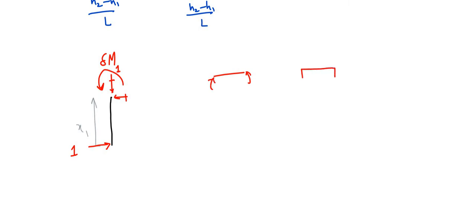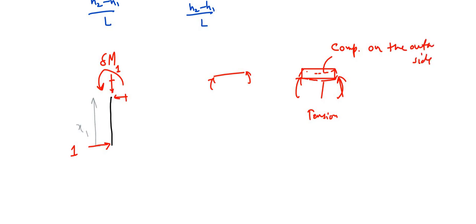अच्छा ये बात भी याद रखिएगा कि हम फ्रेम के अंदर जो पॉजिटिव बेंडिंग है बीम में, तो आपको पता है कि बीम में हम ये पॉजिटिव बेंडिंग लेते रहे हैं, यानी जो मोमेंट की डायरेक्शन है, इस डायरेक्शन से जो स्ट्रेसेस प्रोड्यूस होंगी, ऊपर कंप्रेशन प्रोड्यूस होगी, इस तरफ कंप्रेशन, और इस तरफ टेंशन प्रोड्यूस होगी. तो अगर आप बीम में देखें तो पॉजिटिव जो बेंडिंग मोमेंट है जिसको हम सैगिंग भी बोलते हैं, it produces compression on the outer side, ठीक है.